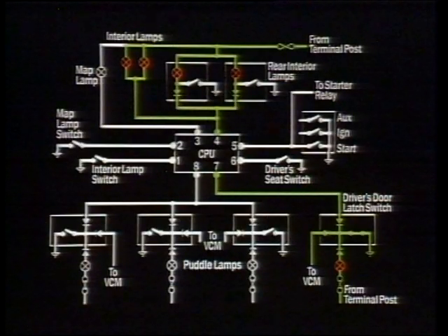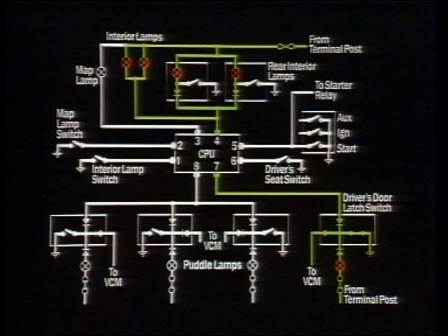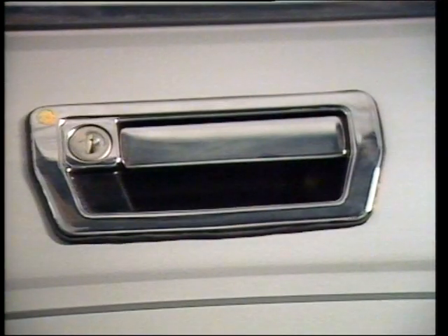If the driver opens the door but doesn't get in, the seat pad switch will not be activated. If the door is left open, the CPU will operate a 2-minute timer. If the driver's door is opened but closed before he gets in, the interior lamps are on a 15-second timer and so stay alight. True or false? Okay, the interior lamps are not on a 15-second timer. The interior lamps are on a 2-minute timer and so stay alight. True or false? Yes, you've got both parts of the question correct.